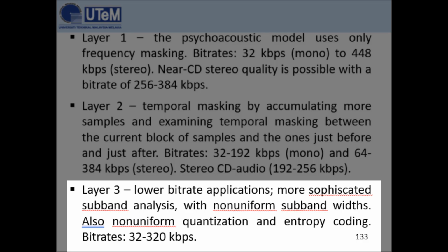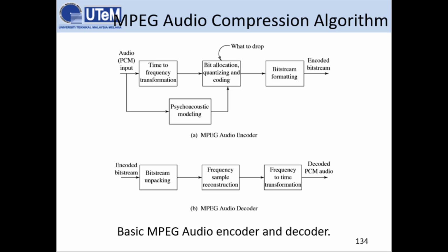Also, non-uniform quantization and entropy coding such as Huffman is added. Huffman coding is added in the layer 3 encoder. So this is the overall algorithm for the encoder and decoder of the MPEG audio compression method.